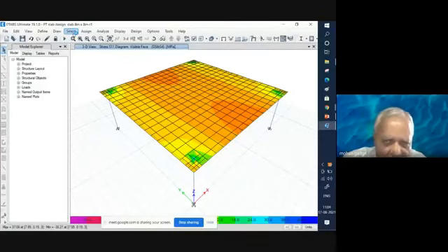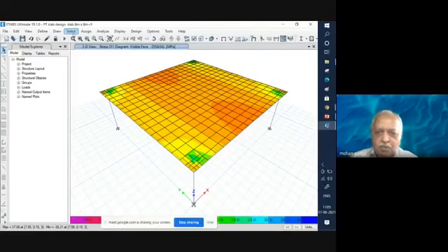That can be anything. Later on you can always revise if it is not satisfactory, and you have to define the profile. So once you draw the profile, you go back to that menu and then define carefully the profile, and then multiple tendons can be drawn in that particular case, and then you are able to directly consider the solution of the problem in this case. If the results are satisfactory, then you are okay. If results are not satisfactory, you go back to revising slab thickness or revising tendon number or sizes and so on, and then you are ready with the final design.